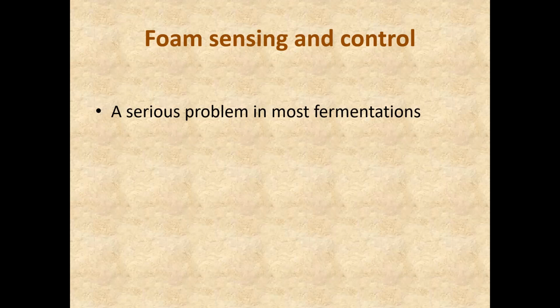If uncontrolled, this foam may cause serious problems, physical and biological. To name a few, this may cause reduction in the working volume of the fermenter, invalid process data due to interference at sensing electrodes, so incorrect monitoring and control. Cells get deposited at the upper part of the fermenter. The air filter exits become wet. All these things lead finally to loss of the product or fermentation. So foaming is not good and it has to be controlled.